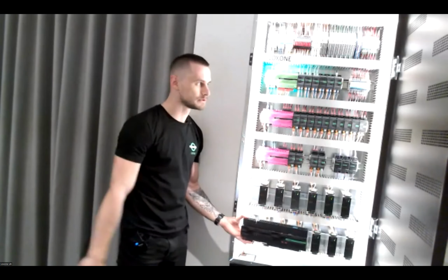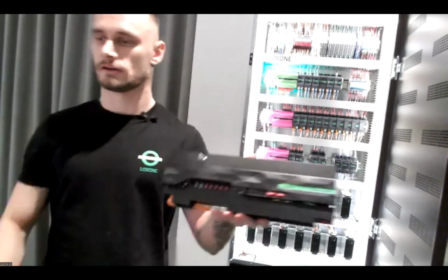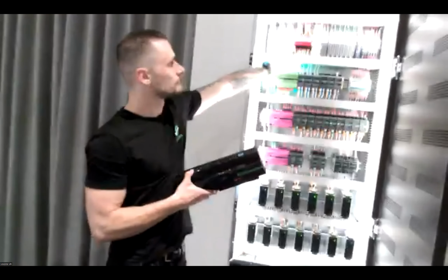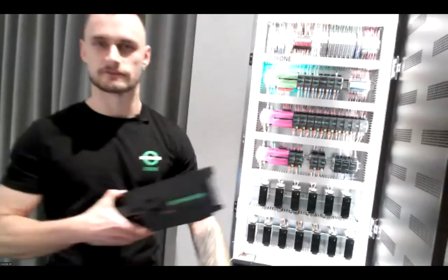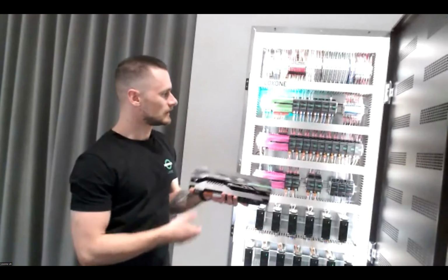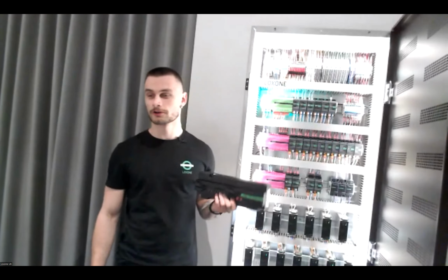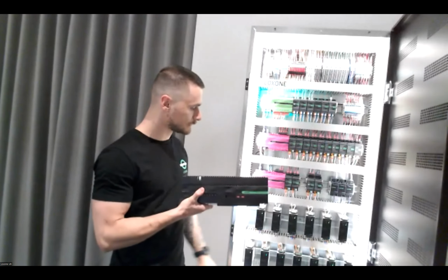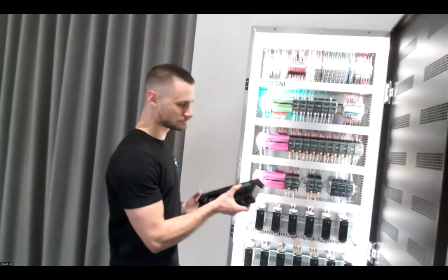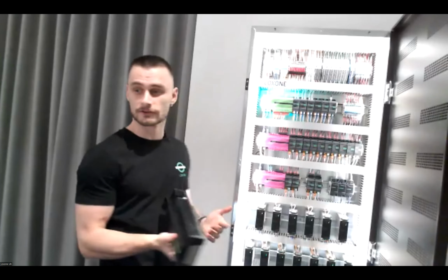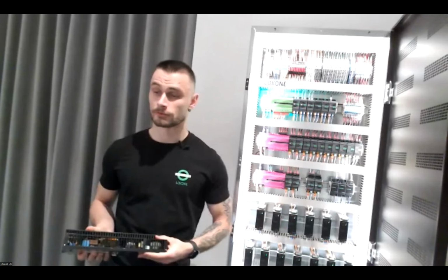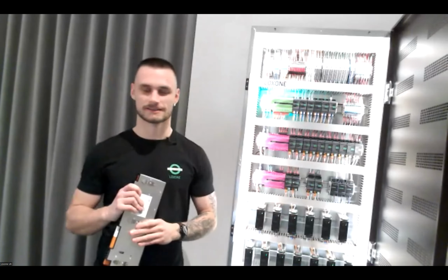So side-by-side comparison, if I slap it in, or maybe in here so you can better visualize it, that is going to get rid of 2 DIN rails because of the fused-in terminals. We're also going to get rid of quite a few terminal blocks on the top. Well, that is very, very blown out. A few terminal blocks on the top, and overall that panel is, well, it's not going to be reduced in size by half, but we're definitely going to have 1 DIN rail just sitting in there, and we'll be able to have a little bit more room for any future products that come to us, and we'll be able to install them in our project without thinking, oh no, where am I going to fit it, I don't have enough space.